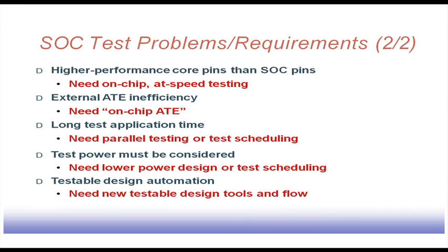Higher performance core pins than SOC pins. So, basically what can happen is that the SOC operates at some frequency, and when we are doing the testing in particular, these SOC pins are operating at some frequency, but internally the cores can operate at a much higher frequency.